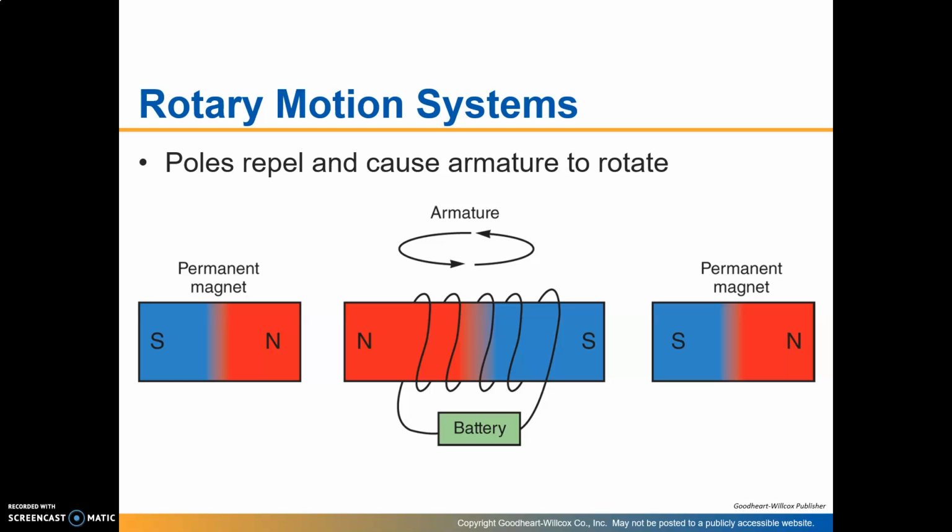And in a non-permanent magnetic material, those things are all jumbled together and pointing in all different directions. And it takes that electric field to line them all up nicely so that they can create a nice strong magnetic field. That strong magnetic field then interacts with the permanent magnets that are on either side of the system and creates a torque, creates a moment to spin that armature around, because obviously we've probably stuck a dowel in the middle of that north-south center pole there, right here, that would cause this to rotate.